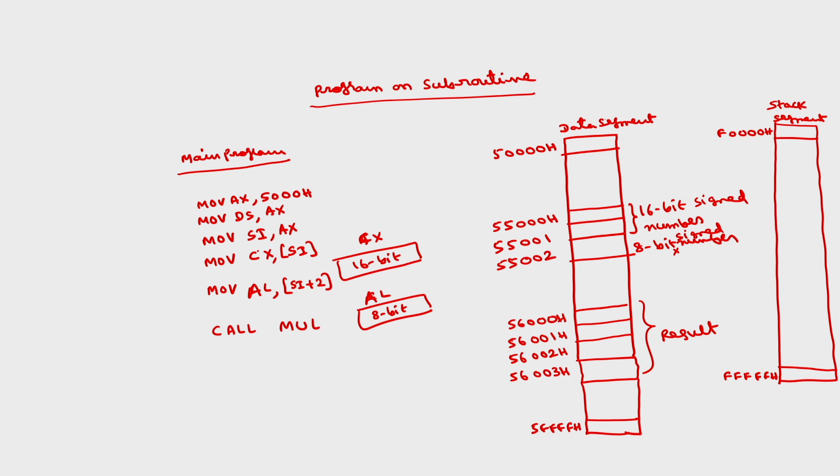Okay. So in this we have to define the stack pointer, till which point the stack is full. I will assume that up to here, say, the stack is full. So if this is FD00 or some 2, up to this the stack is full.